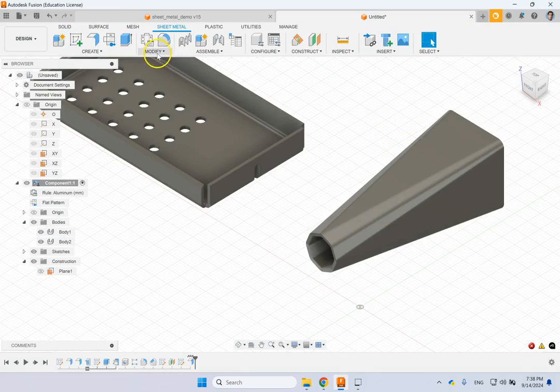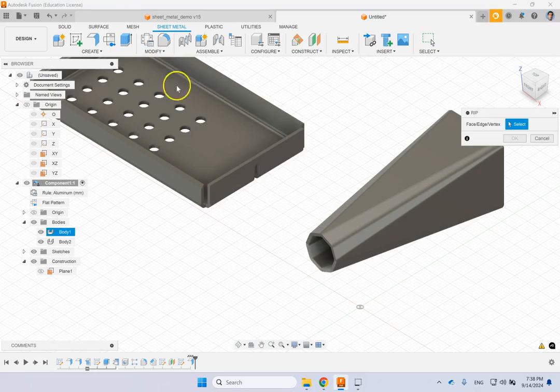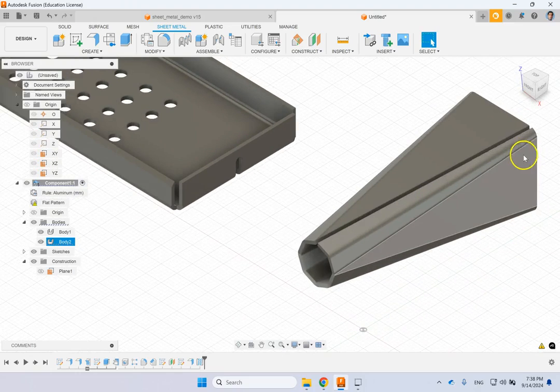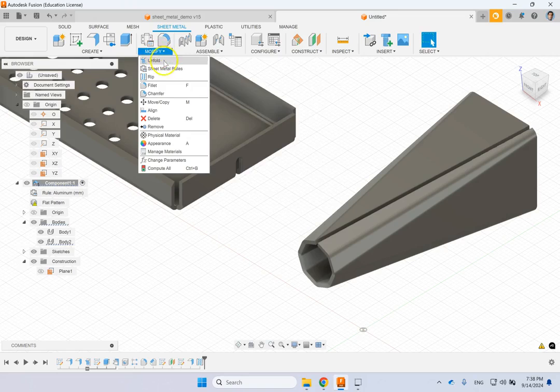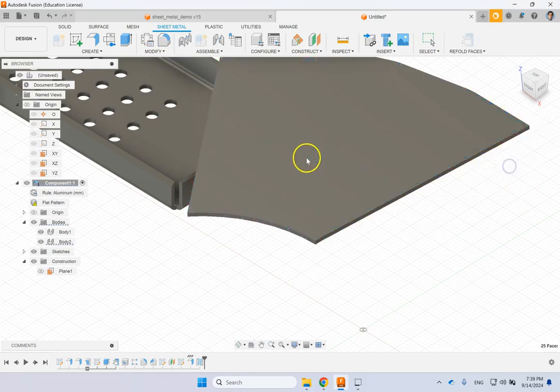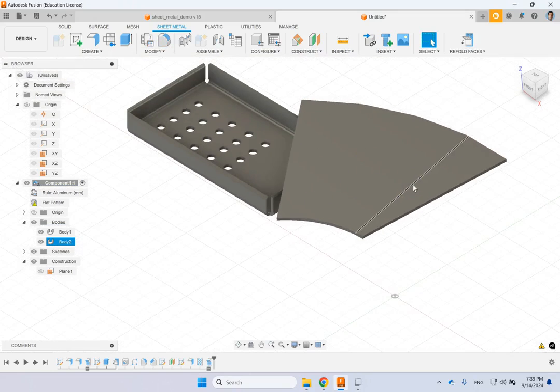If I do a rip in it and take a small portion of it off, create a line in it, so say I want to do a rip on this, align, let's say this line with a gap of only 1 mil, and create this gap, you see now the sheet metal is opened. And now can I unfold this, or can I open this? So let's say if I want to unfold this and I want to pick that, you see here, now I can have the stretch of it. Okay, so it is doable.